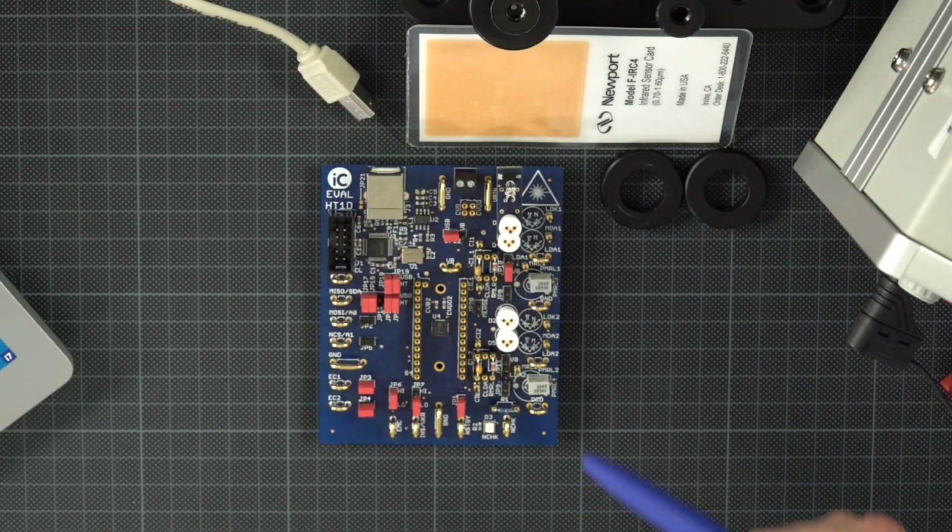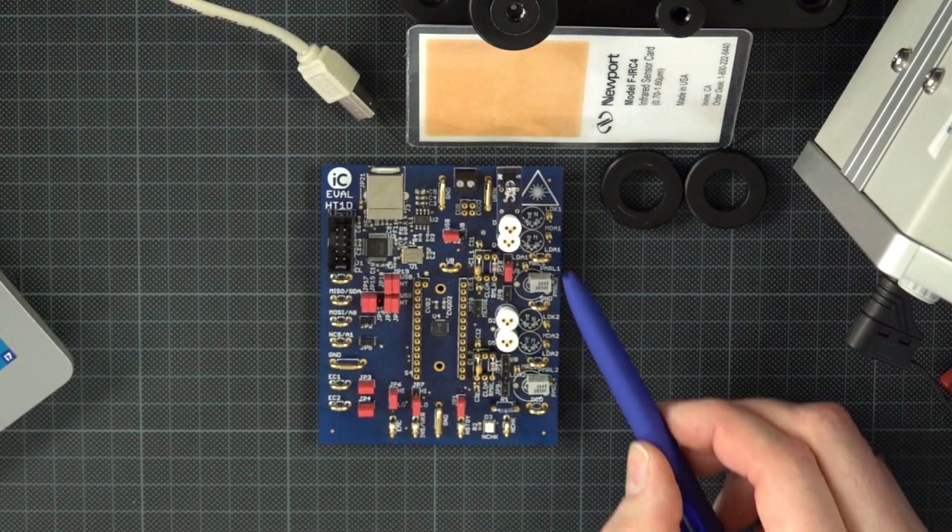The sockets for the exchangeable parts are not important for now, as we are going to exclusively use chip internal control. At the lab power supply, the voltage for the laser diode circuit needs to be set. I set this to 3 volts. That is the sum of the forward voltage or operational voltage of the laser diode plus 1 volt due to the saturation voltage of the iC-HT. Here, of course, it's the forward voltage of the dummy replacement.